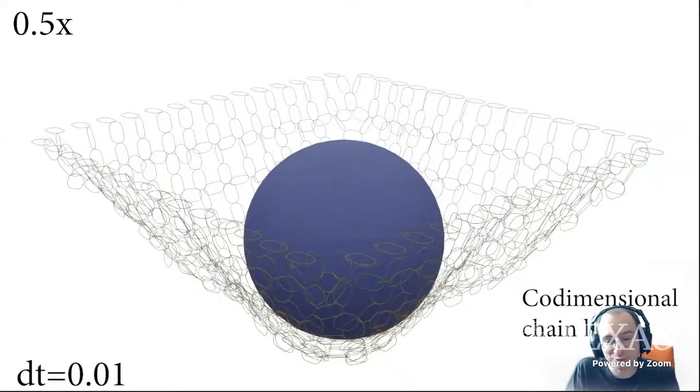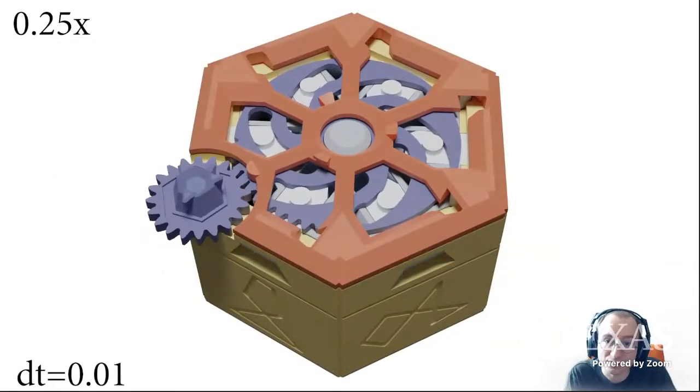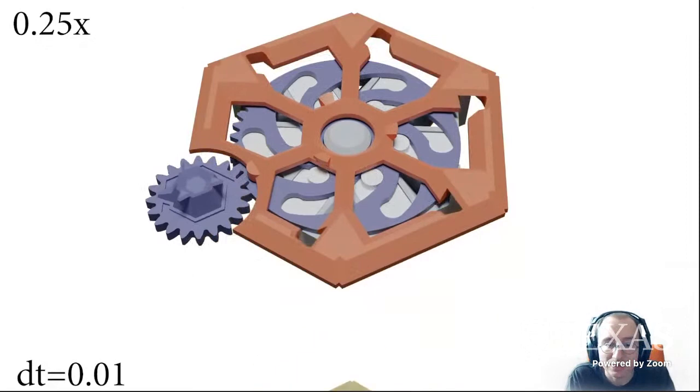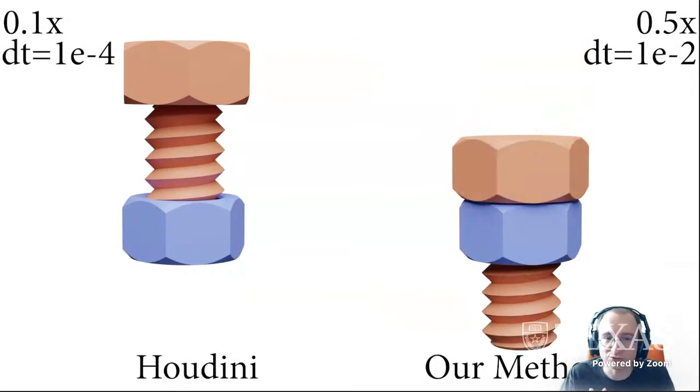Yes, in that case, you'll probably want to be able to differentiate through these blocks, which, at least for the tetrahedral meshing method that I showed, cannot be done right now. But one of the cool features, which I actually didn't mention yet, that we briefly discussed in the paper but haven't used for anything yet, is that the formulation of IPC, the one you're seeing here in this video, the entire formulation, both the deformation part and the contact response and the time integration, is all differentiable. Not formally, but for practical purposes, it is differentiable.